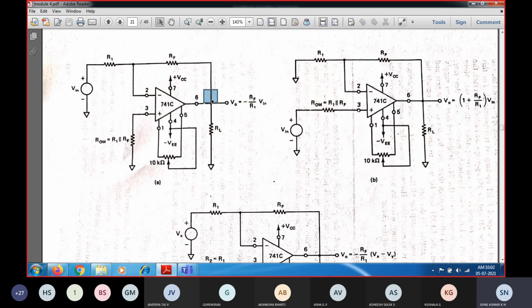So we need to reduce that biased voltage by however much it has increased. If the output voltage is positive, we need to get it back to 0, which means reducing the output voltage. For that we use the offset nulling terminals provided by the manufacturer for some operational amplifiers, terminal 1 and terminal 5.